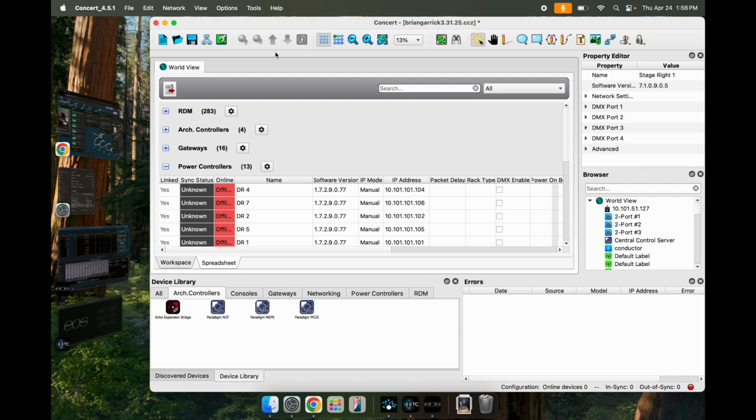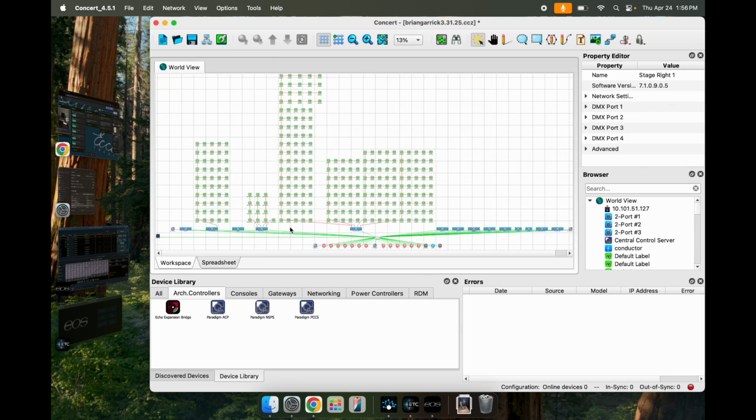Sometimes the devices get a little funky when they're trying to connect to the lighting system. I always just find unplugging it from the Ethernet port and plugging it back in helps. They're all powered through Power over Ethernet, so just turning it off and back on again will make them start thinking and get them back on the network.